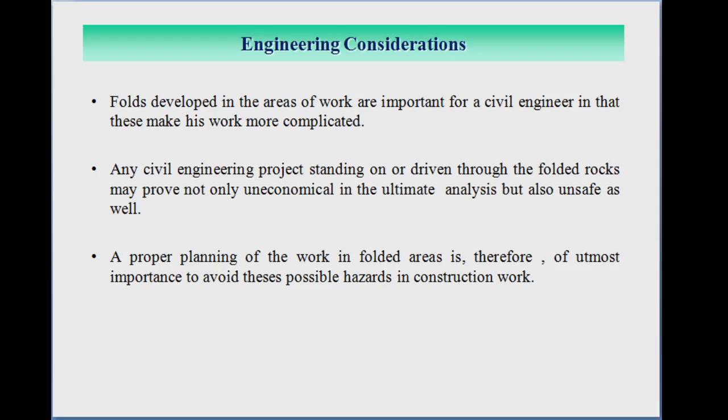Due to all this, attention must always be given to the presence of the fold in deciding about the design and construction of such structures as driving of the traffic and hydropower tunnels, selection of the dams, reservoirs, and fixing the alignment of the roads, bridges, highways. The study of this rock is done in detail. The influence of the folding on the design, stability, and economy of the structure has been discussed in some detail.